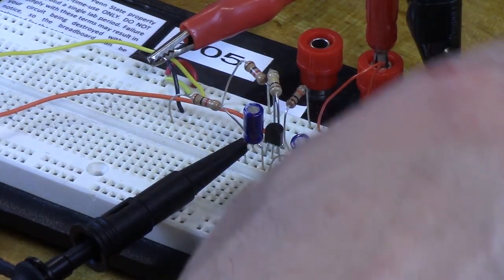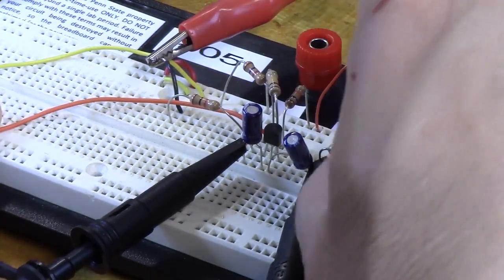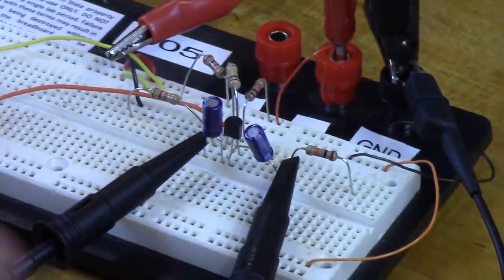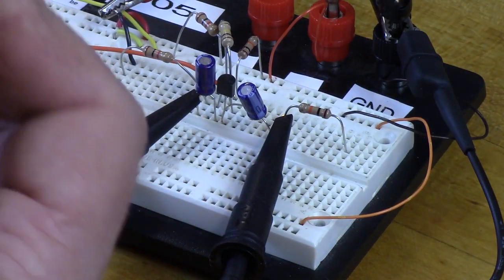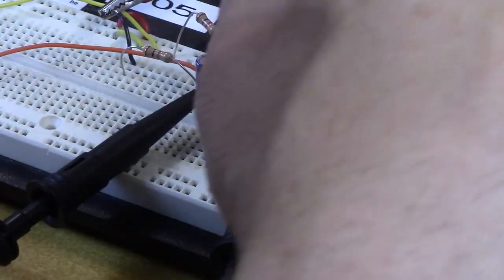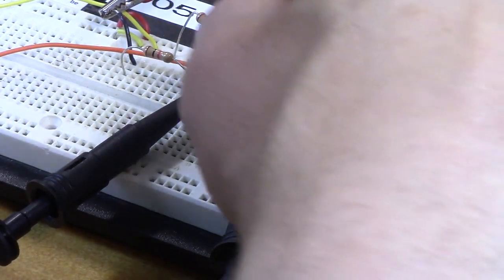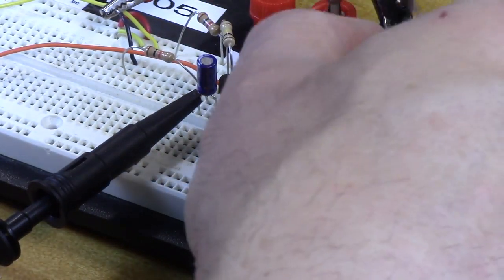So what we'll do is this 10K resistor is a convenience for us in that it gives us a place to hook the probe. So I'm just going to temporarily unplug it. Okay, and just plug it in an empty space. And we now have a 10K pot to do that. The reason I chose 10K is because 10K is about the expected output impedance. I guess a 20K pot would have been ideal. We'd like the middle of the pot to be where we expect the output impedance to be. So there, and then the center lead, the black lead, goes to ground, there.